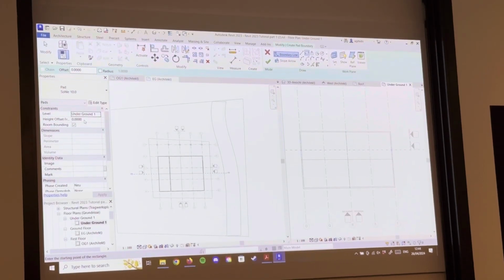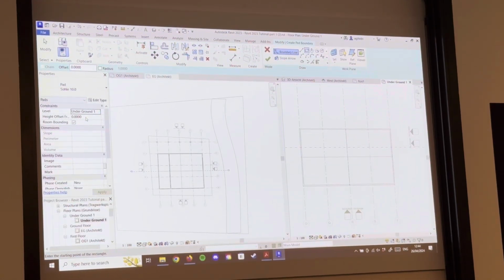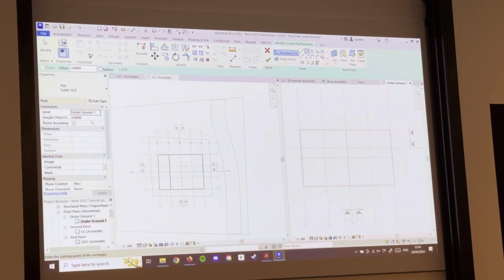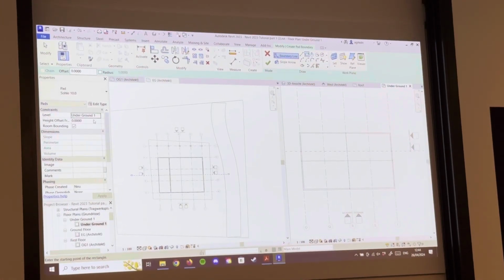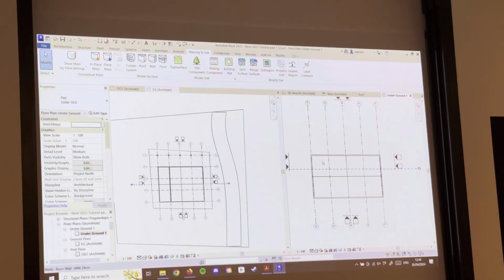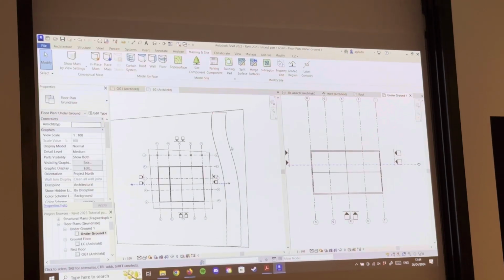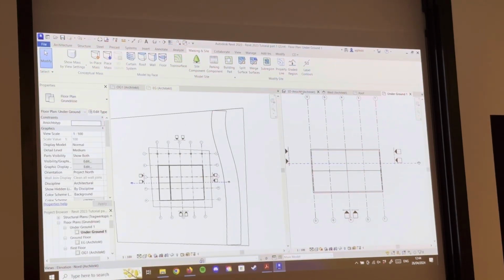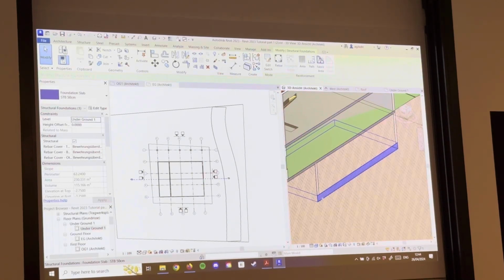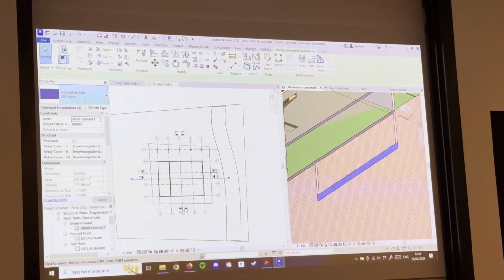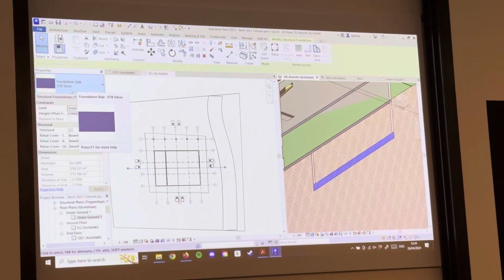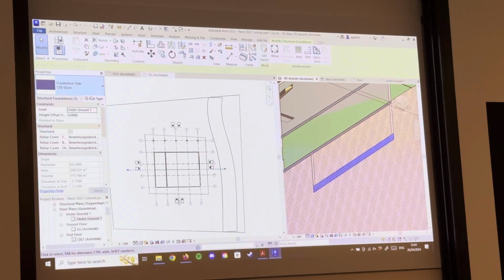If you remember, when we placed the slab for the basement, we also placed it on 0, 0. Maybe if we place it on 0, 0, they're going to clash with each other. So what we could do, I can stop creating this because I'm not sure what's the thickness of this slab, and I can go to the 3D view again and just click on the slab in order to see how thick it is. Here the name suggests that it's 50 centimeters, but you never know, maybe it's named incorrectly, so